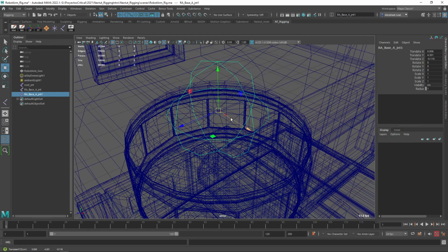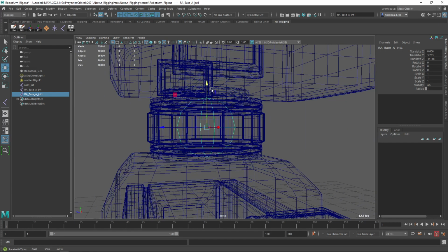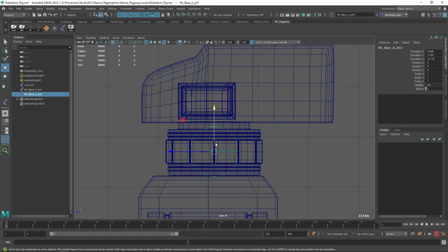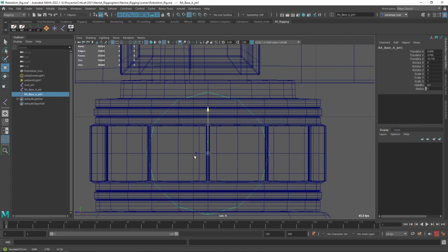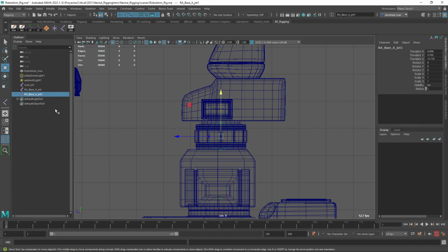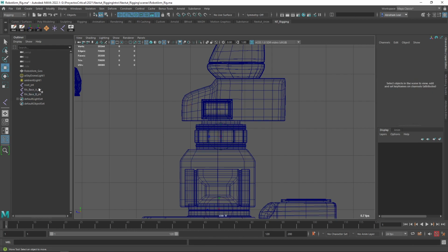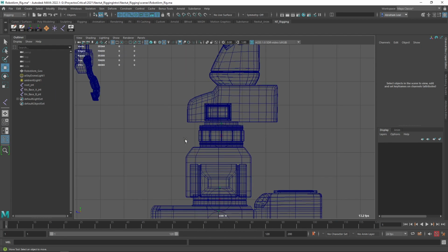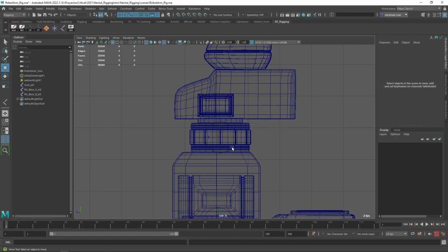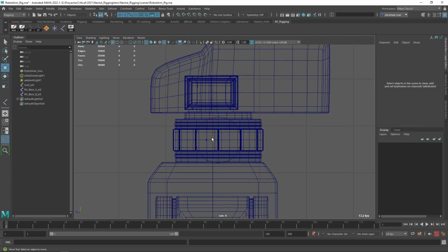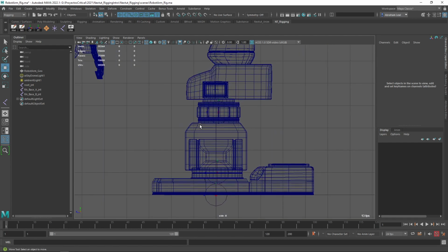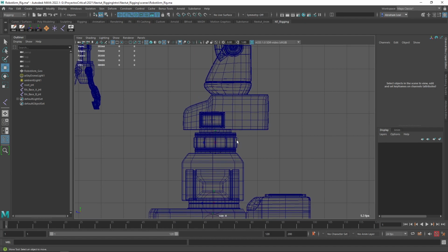Now we're going to duplicate, move up, and we have this next part, which again we can snap our joint to the center right there and move it as close as possible to the center line. Doesn't have to be perfect, don't worry. You can snap it, of course. Like if we snap, that's going to be dead center, so that works fine. And this is going to be robot arm base B joint, and that's it. That's why it's very important to have clean names, because eventually we're going to be doing the skinning, and in order to clean the skinning in the best possible way, we need to make sure that things are working very, very nicely. So there we go. Our base A joint, base B joint, and we're ready. We're good to go. We can continue.